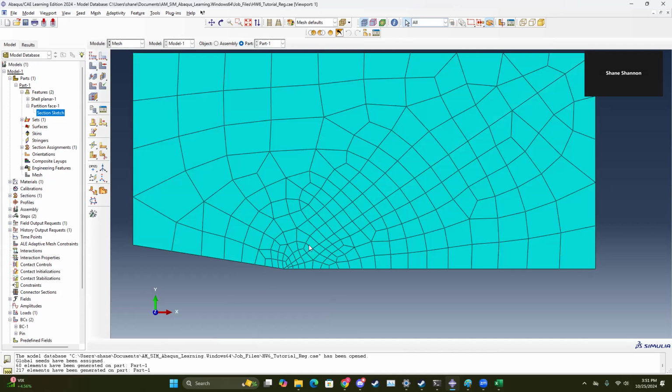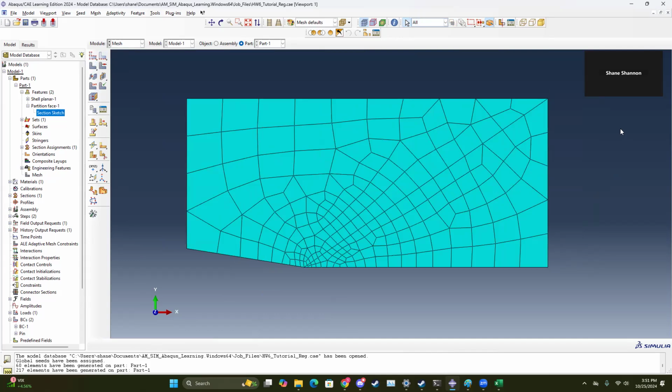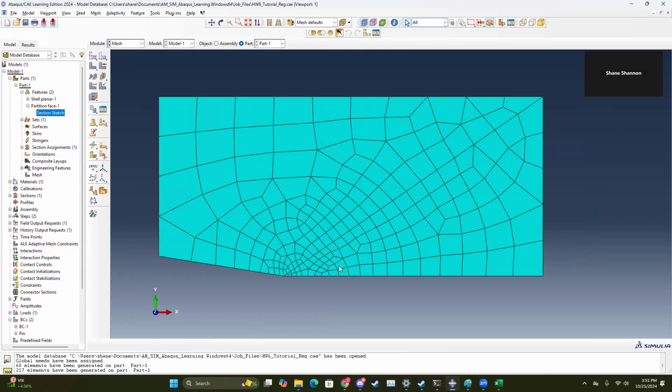And look at that. It's nice and dense in this area, and further along, it's thinner where we don't have to pay attention to anything. And now we're making the most out of the number of nodes we can use. Obviously, you can change the number to get a lot thinner, thicker, add another reference line, I suppose, going in the complete 90-degree direction, whatever you guys want. But that's essentially how we do that.